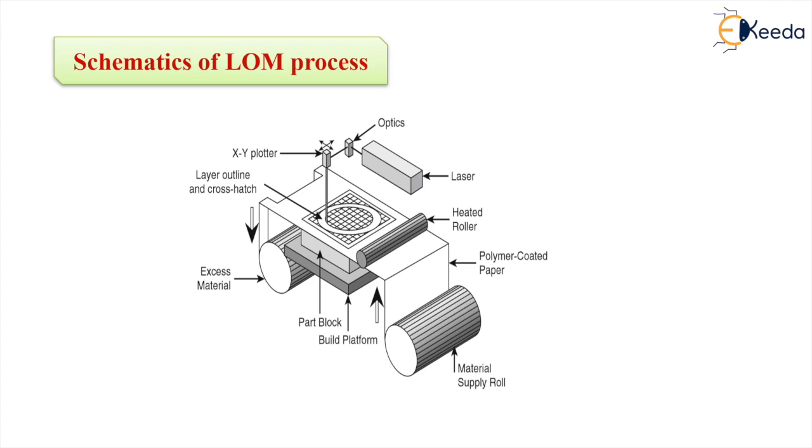Once the shape of the new layer is traced and cut by the blade or this laser, and the new layer is completed, the building platform, you can see, is going to descend and new paper is added or supplied.